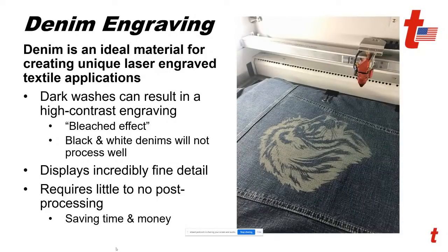Again, the engraving won't come out as light until it's dried. So make sure you've dried it out to make sure your setting is right. Don't just assume you've hit it with too much or not enough power when you processed it.